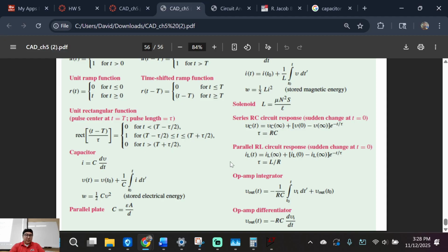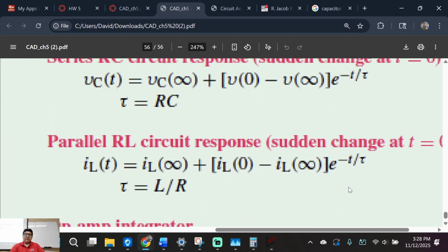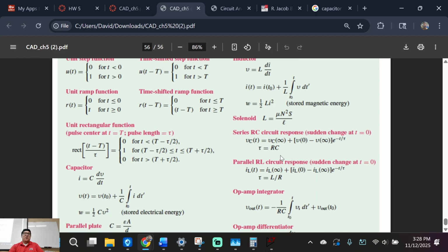Okay. Does everyone know how to use these governing equations over here? Right? This is a bad screenshot. Easy, just plug and chug, like the last class we did last week. It wasn't that bad. You just find your RC, and if you needed to, you can solve for a Thevenin circuit to find the total resistance so you can find that time constant RC. Is that good?